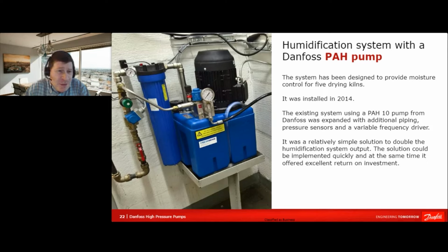Also Kent mentioned this power pack valve, which you can see behind this manometer here. I think it's a very clever system for lumber drying applications, because you can spray very short cycles of water and immediately have the needed pressure in the pipes. Even when it's bypassing, it's going through the open valve, so it's not increasing the energy cost the way a pressure relief valve would. So this is a very easy and clever system for these kinds of applications. Thank you, Kent.